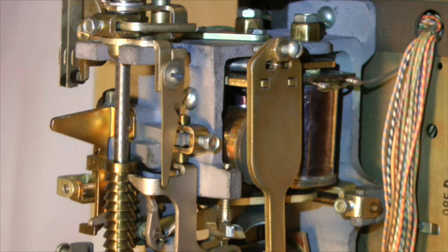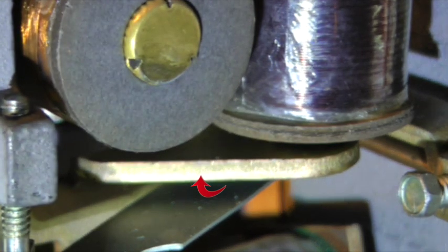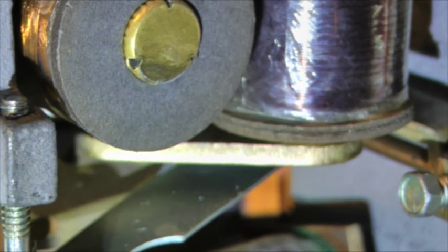The vertical magnet is energized or magnetized each time a vertical step of the shaft is required, and de-energized or demagnetized after each vertical step is completed. It has an armature that is attracted to the 2 coils each time they are energized, and which pivots back to its released position each time the coils are de-energized.